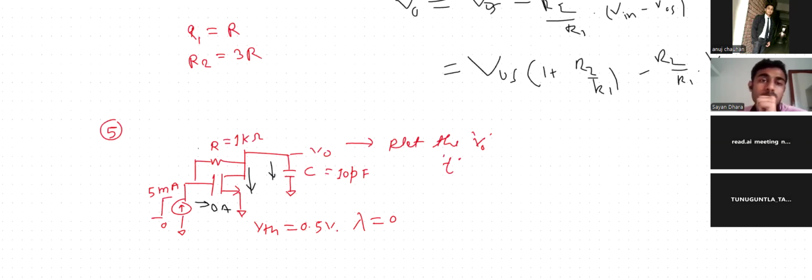You note it down in a notebook and we practice it in free time. Analyze it properly. Let it be an RC circuit, and the extra thing there is only the MOSFET. Rest everything is simple R and C. Step current. What is step current? So at that instant, at t equal to 0, this would be the short circuit. So VO would be 0.